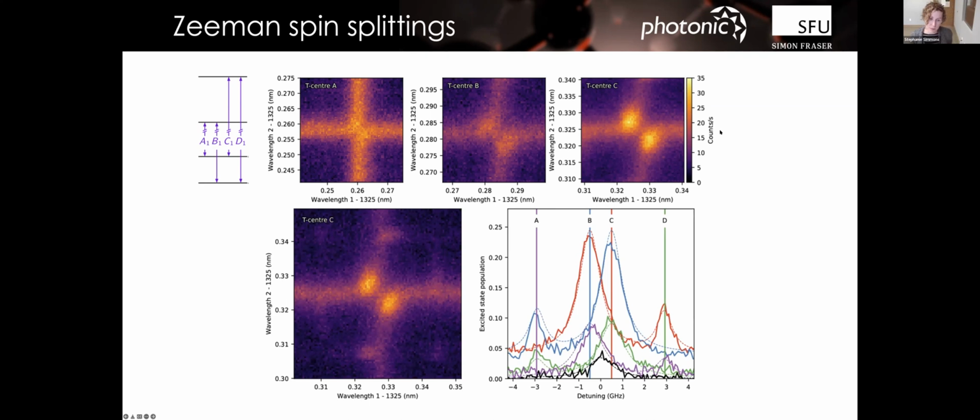And I'm not going to lie, these counts per second are brutal. We've since improved it quite a bit from the initial, but this has to do with the fact that, of course, silicon does not like to spit light out, and these things don't start off natively terribly bright. It's about a microsecond luminescence lifetime. So that's what we were starting with. We've since improved it quite a bit, but that's what this initial publication had.